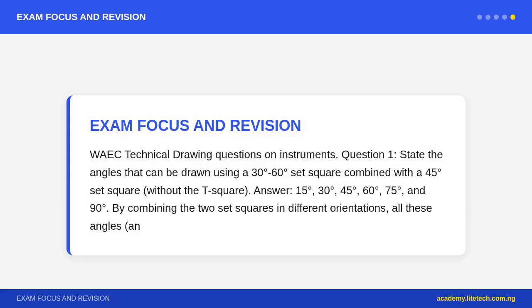Question 5. What is the purpose of an erasing shield? Answer: an erasing shield is a thin metal sheet with various small openings, rectangular and circular holes. It is placed over the drawing to cover and protect lines that should be kept while allowing the eraser to reach only the line being removed. This prevents accidentally erasing correct lines that are close to the line being corrected.